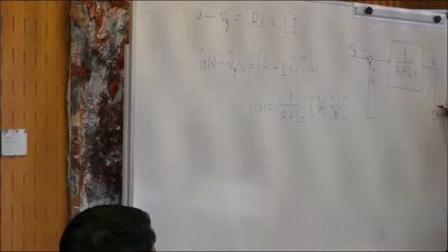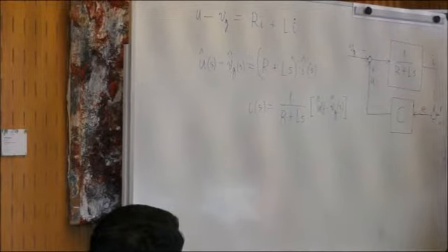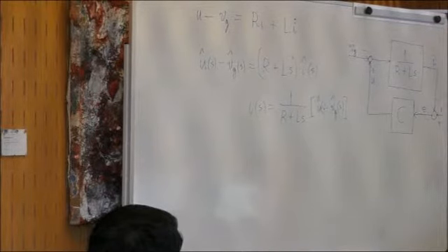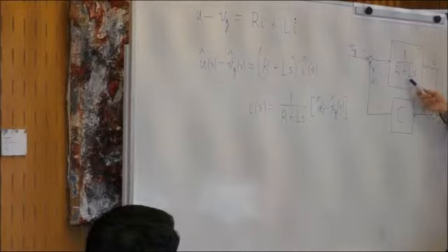And now this is a tracking error, E. And now we want a controller here, so that this tracking error should ideally tend to 0. Right? So this is now the diagram. After you write it like this, it's a very simple problem formulation. You have a plant which is a transfer function of order 1. Yes, stable, obviously stable.